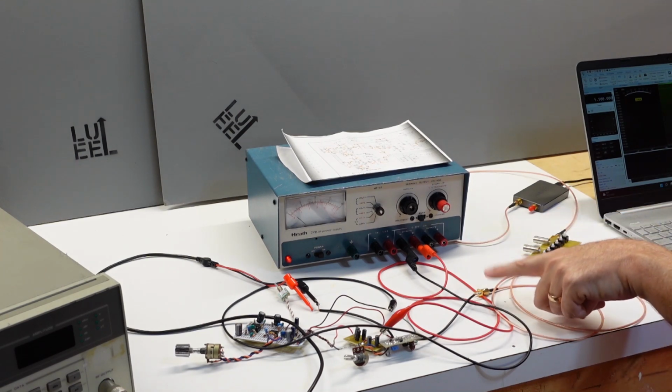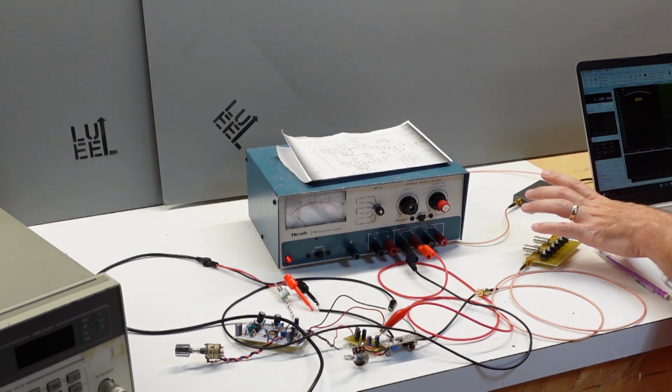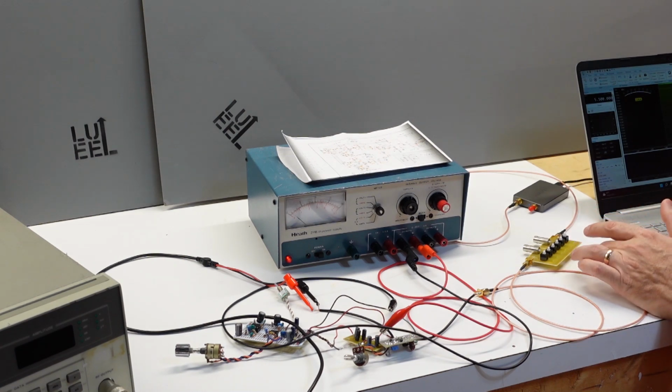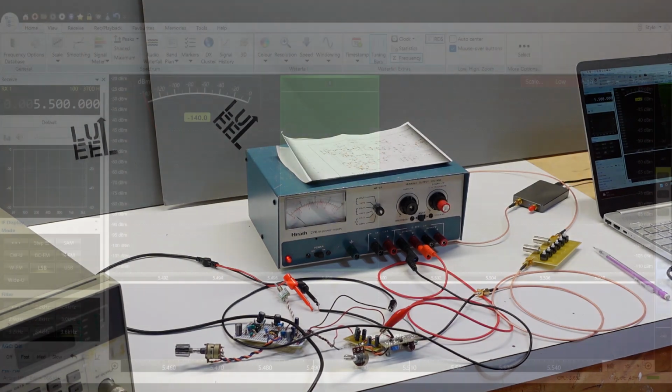The output of this guy is, of course, minus 20 dBm, and the AirSpy will handle up to plus 10 dBm, but I didn't want to push it that far, so I put in a step attenuator so I can dial it down about 20 dB or so. And then I'm just using plain old SDR Console to look at, again, qualitatively the signal that's coming through all this chain. And I think it's pretty interesting what we can see even with just this limited qualitative view.